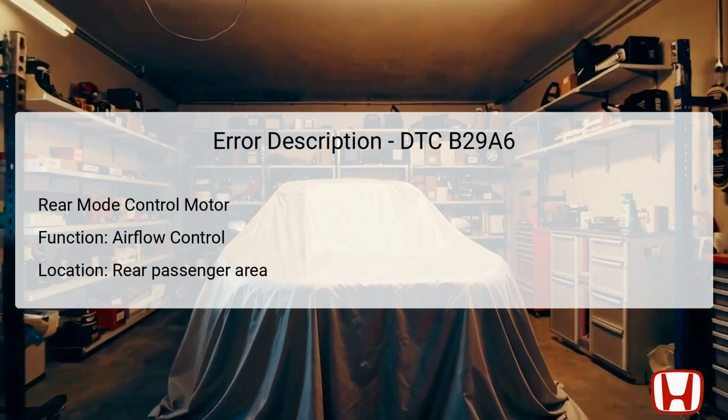The DTC B29A6 indicates a problem with the rear mode control motor circuit. The rear mode control motor is located in the rear passenger area of the Honda Accord as part of the climate control system. Its primary function is to manage the direction of airflow and maintain the desired temperature by adjusting the blend doors within the heating and air conditioning systems.